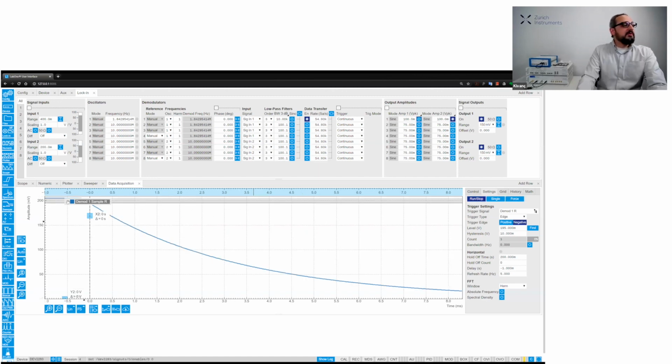All right, so this is what I'm talking about. At this moment, we were driving the oscillator, so it was a bit above 200 millivolts. And at this point that I'm showing now, we stopped the drive and the oscillator relaxed. You can see that, since we have a high quality resonator, we have a relatively slow decay that spans over a few milliseconds.